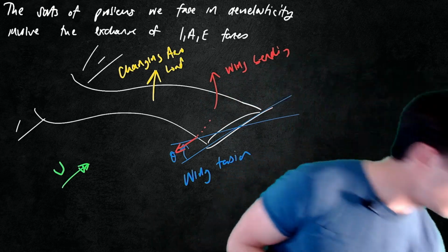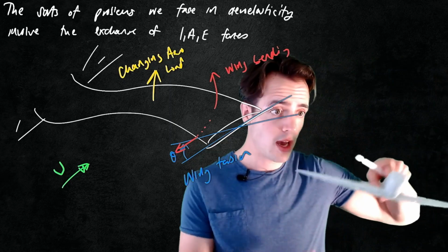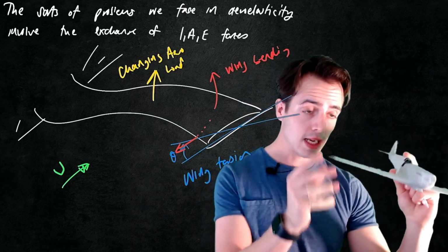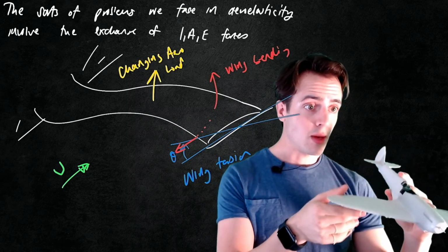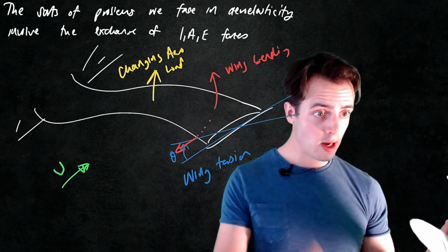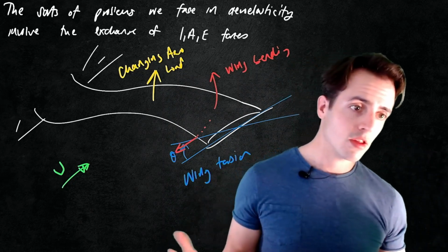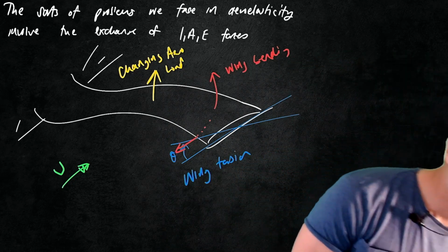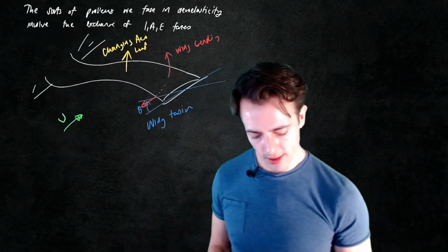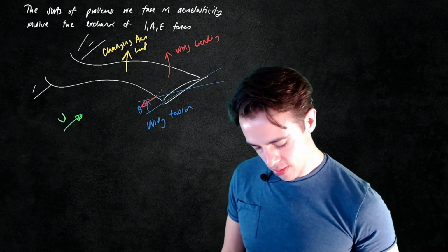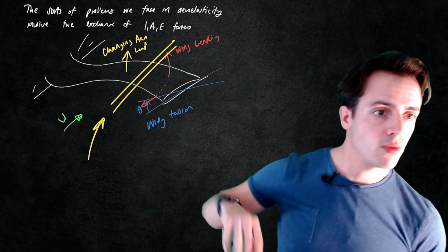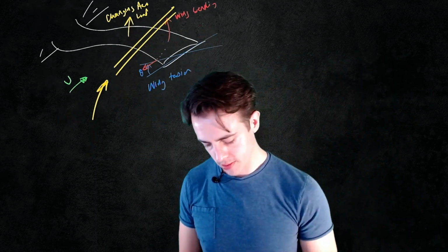If we have a wing that is bending, so let's pretend rather than this being a roll motion, this is because of wing bending. It will cause a plunge velocity. It will cause an effective change to angle of attack. When the wing's undergoing torsion as well, that changes the angle of attack, which changes the forces on the wing. So we need a mathematical model of this sort of problem. And we can do that. We can take a representative section of the wing and make a two-dimensional model.